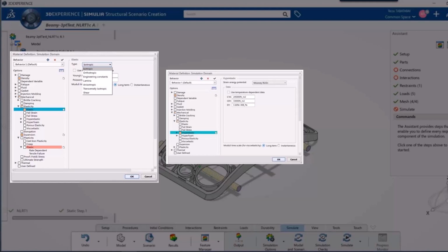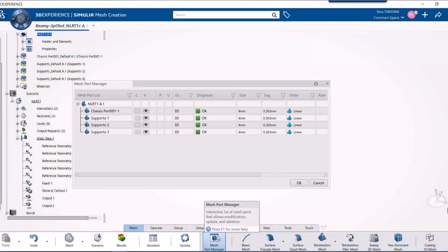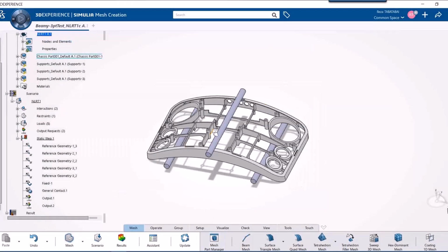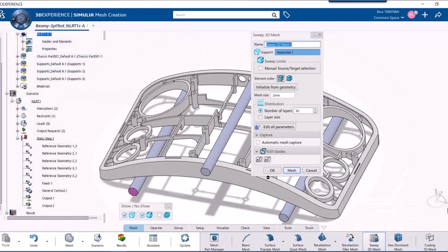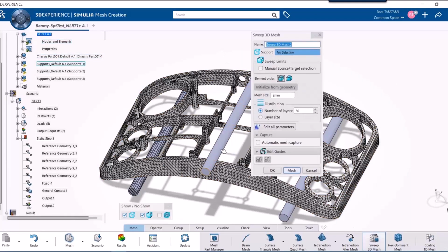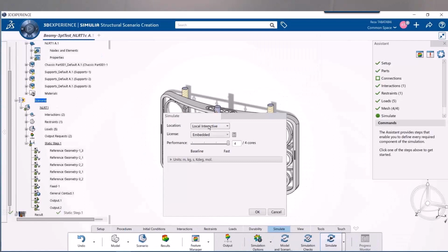Of course, we have a handful of nonlinear material models inside of Simulation Premium, but it pales in comparison to what can happen over here, where we've got Abaqus multiphysics materials. Meshing as well can be done, of course, with tetrahedrals for complicated geometry and automatically mesh just about any shape, or you can switch to things like brick and quad meshing, even continuum shell meshing.